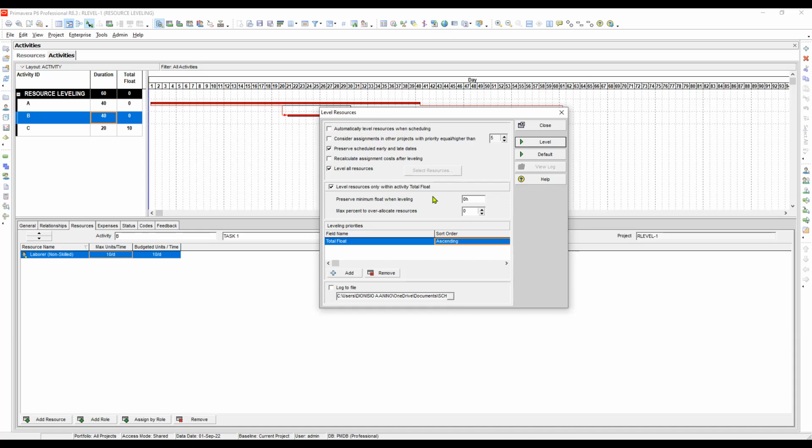You must not affect the established completion. Let's say, for example, the completion is 300 days for a specific date, you have to maintain that date, so you run the leveling of the resources without affecting that completion date, because that is a contractual requirement.